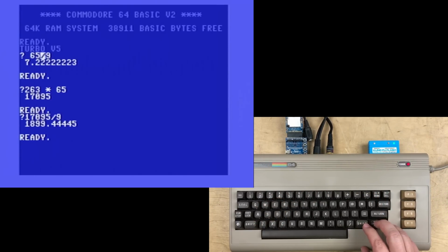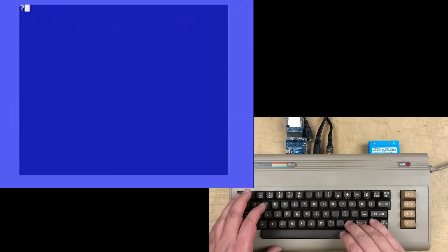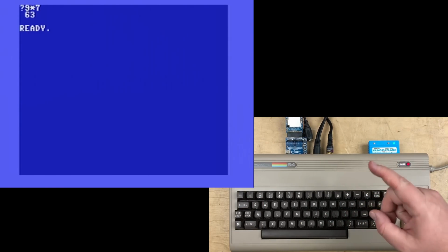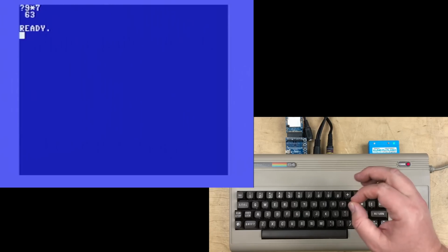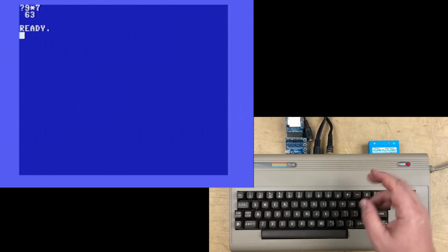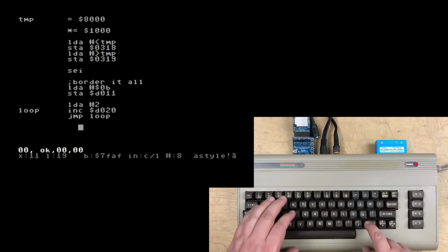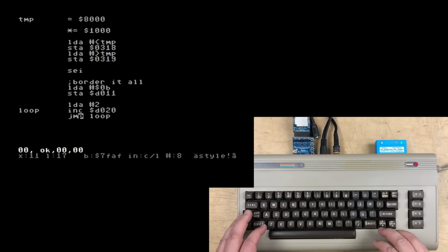Okay, but that loop happens to take 9 cycles. Well, 9 times that same 7 is 63 cycles. That just happens to be how many cycles are on a PAL Commodore 64. 63 cycles per line. So I'm going to switch to that. Okay, here's the Swedish C64. Thanks to Magervalp. Okay, exactly the same code we were just looking at. But let's see how it reacts on the PAL C64. Back arrow 3, start. And instead of a wildly scrolling screen, we get this incredibly stable image.